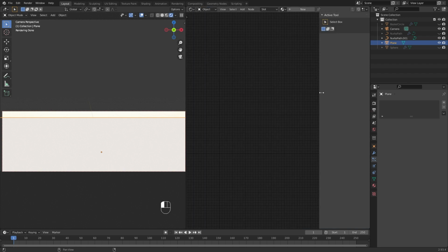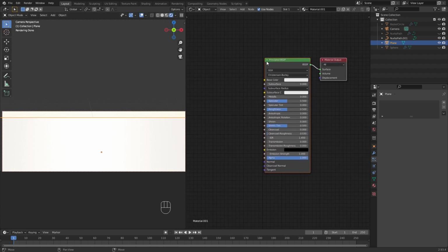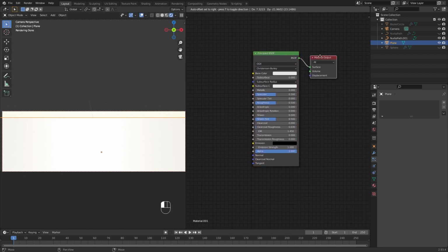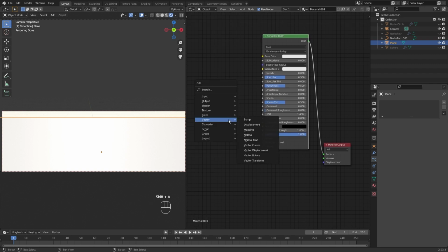Now let's create the materials for this. Here, we want to render this ground as a glacier land. For this, we will use a displacement map to get the depth details of the land. So, now add a noise texture and set the node preview to it.